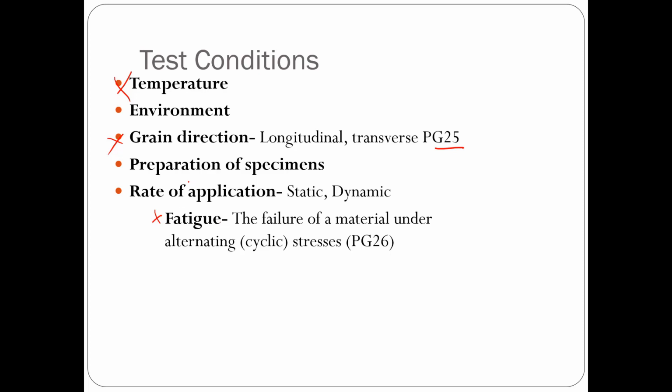So I mention that once in a while, like I said earlier, that the longitudinal direction is going to have better fatigue life, and then transverse, and then through thickness, which is not listed here or in the book, but we talked about it, we need to know about it. Our through thickness has the worst fatigue life. Why is that important? Because that's the number one reason why materials are going to fail.